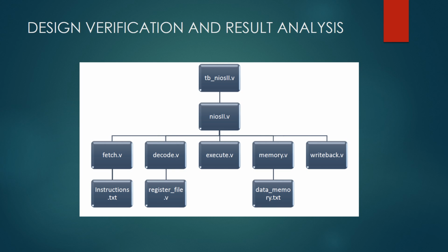In order to ensure the entire design works perfectly, it is important to verify each module separately to ensure correct working of all its functionality before integrating all the modules. This is done by writing separate test benches for different stages of the pipeline. After completion of all the stages, we get a complete integrated design of our main module.